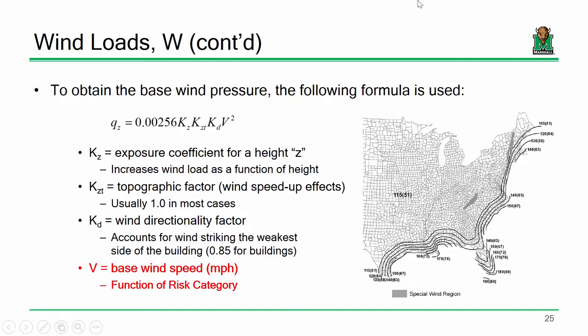The question was, what's the deal with wind and piles? If you have wind striking a building, think of the building as one large beam, almost like a big cantilevered beam. Part of the building would experience compression at the bottom, and part of the building would experience tension. So it's possible that you could have some uplift effects on your piles on this side of the building. But you also have to keep in mind we're talking about wind effects versus the massive weight of the structure, so that really probably wouldn't happen under wind.